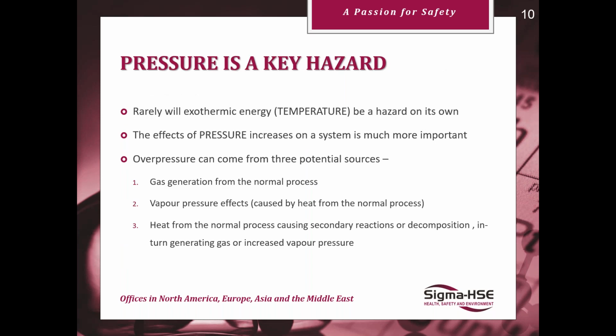So I'm sure, as you can imagine, pressure is a key hazard. Any kind of vessel which overpressurizes, you're going to either be able to slowly vent it or you're going to have an explosion. So rarely will exothermic energy or the evolution of temperature be a hazard on its own. The effects of pressure increases on a system are much more important in terms of minimizing risk.